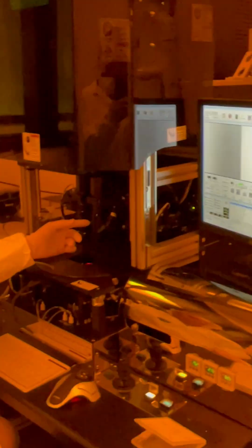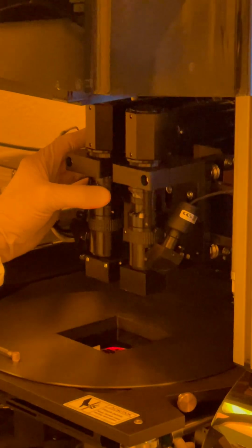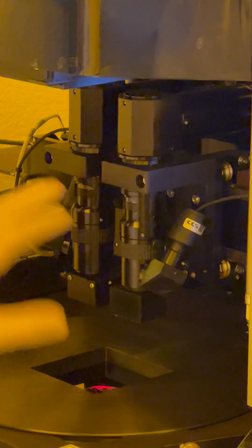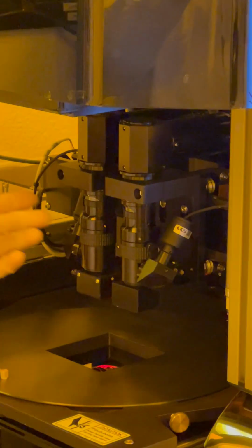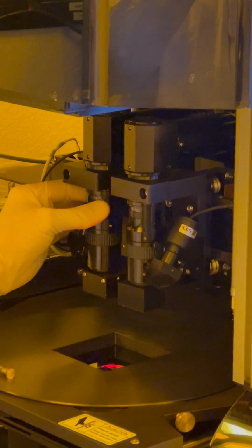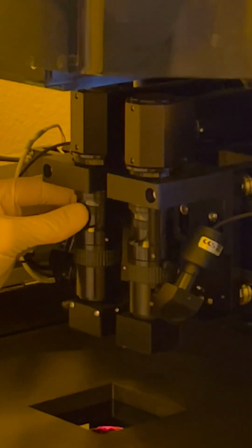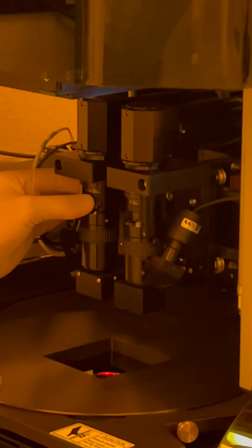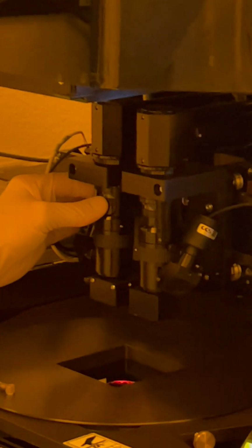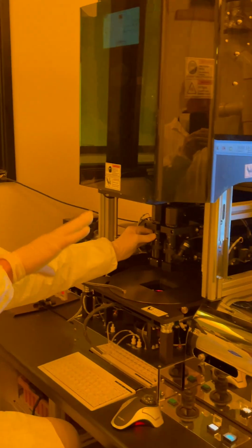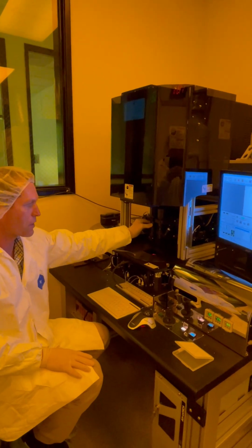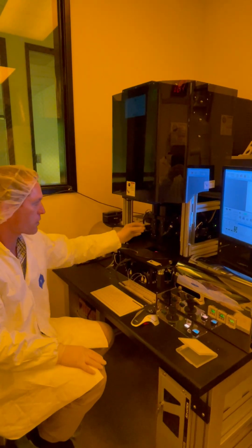The microscopes have zoom settings on them, and focus. So it's manual focus and manual zoom on top of it. They're detented, so you can adjust them from 1 up to 4, and each setting has a little detent position that you adjust it in, and you need that detent because for each setting there's a calibration for how many microns per pixel on the screen for doing the auto alignment. If you put it in between, then it's going to be between the calibration settings that are stored in the setting.